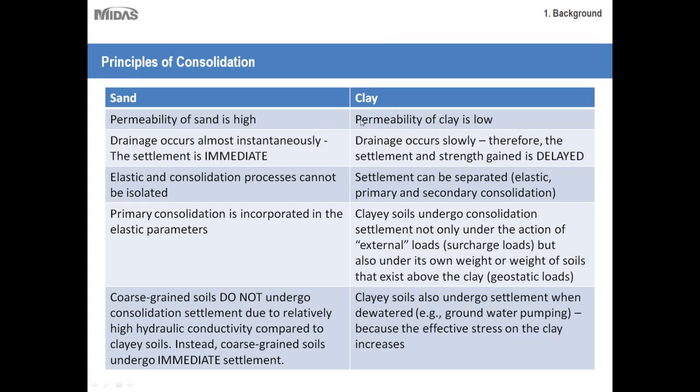So this is directly related to the size of the pore size of clays and sands. Sands have very large pore sizes. That's why drainage happens so fast with them. If you can imagine, if you've ever been to the beach and you've held a handful of sand, you put water through it, water will come out through the other side very quickly.